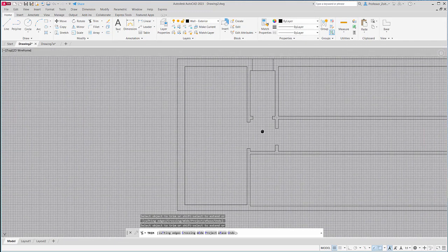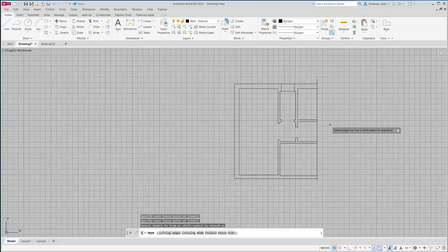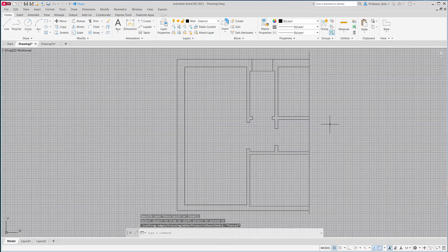It's very easy with all the different line segments that we had in this drawing to lose track of the lines that you need. Now all these lines extend for a fairly long distance. I'm going to pick a location. I just draw a line here, hold down shift, and to give me enough room, I do need a boundary edge when I go to eventually hatch all of this, and I will trim all this information off. And there's my entire diagram. Eventually, like I said, I'll remove this line or I'll hatch up to it so it represents the drawing that we see here. Okay, so let's save this file.